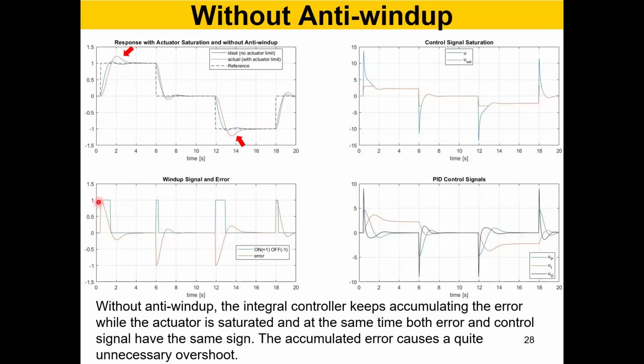And on the left-hand side, you can see the saturation signal. You can see the blue towers here, here, here, and here. When the anti-wind up kicks in, it stops the integral controller in this part, this part. So we don't have to worry. This is kind of done and dusted. Once you do that, right, it will decide when the anti-wind up has to be activated. All right.